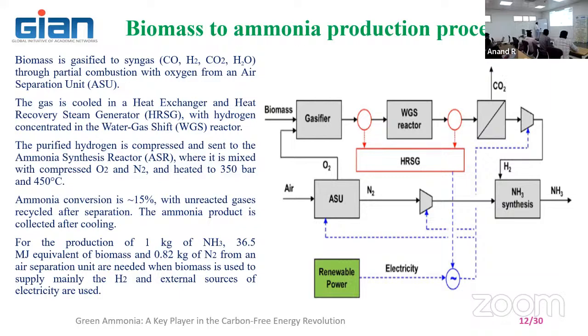Energy content of the biomass is measured by using a bomb calorimeter. A bomb calorimeter is a device used for measuring the calorific value in terms of kilojoules per kg or megajoules per kg. It's a constant volume bomb. This facility is also available in our laboratory. If anybody wants to explore it, you can contact us. We can support. The bomb calorimeter is for measuring the calorific value of both solid and liquid.